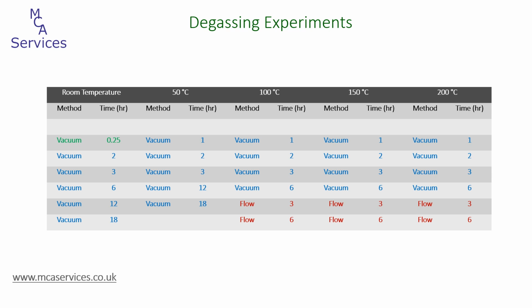This sample was degassed to a minimal extent so that we could investigate the effects of analysing the material whilst as much of the pore volume as possible was occupied by moisture. Now it's really important to note that the easiest moisture to degas had to be removed before analysis. Our TriStar instrument that we used automatically evacuates the sample before analysis, and without any degassing beforehand, this moisture would be removed into the instrument and cause contamination.